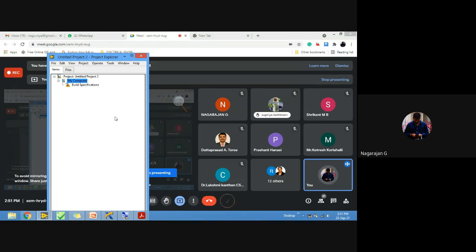We have to go for a buffered data concept, so that each and every data item will be collected and stored in the buffer. From RT, we can get the data from the buffer and process it, so that our entire application will not get disturbed. In order to transfer buffered data between different portions of FPGA VIs, we can use FIFO. FIFO is a first in first out buffer, where the first data item which is stored inside the memory will be the first item which is removed from the memory.